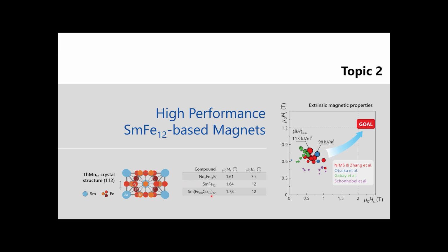Some substitutions are needed with non-magnetic elements, for example, vanadium and titanium, which degrade magnetization and also make it very challenging to control the phase composition and coercivity. So far, the coercivity and remanence of sintered anisotropic magnets are much below what we can get in principle. And if someone can approach this goal, it would complement the market of permanent magnets, and we would no longer see neodymium iron-boron magnets as the prime magnets. We can have a diversity of permanent magnets.